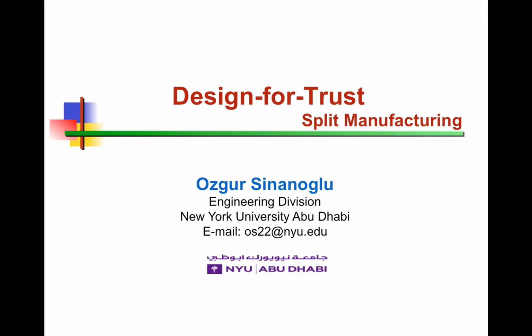So in this module, I talked about split manufacturing. Split manufacturing is the right solution for business models where you trust the end users, the users who will use the devices that your chips will go into, but you do not trust the fabrication facility. Split manufacturing basically hides some of the layout information from the untrusted fab, and this delivers certain security benefits.